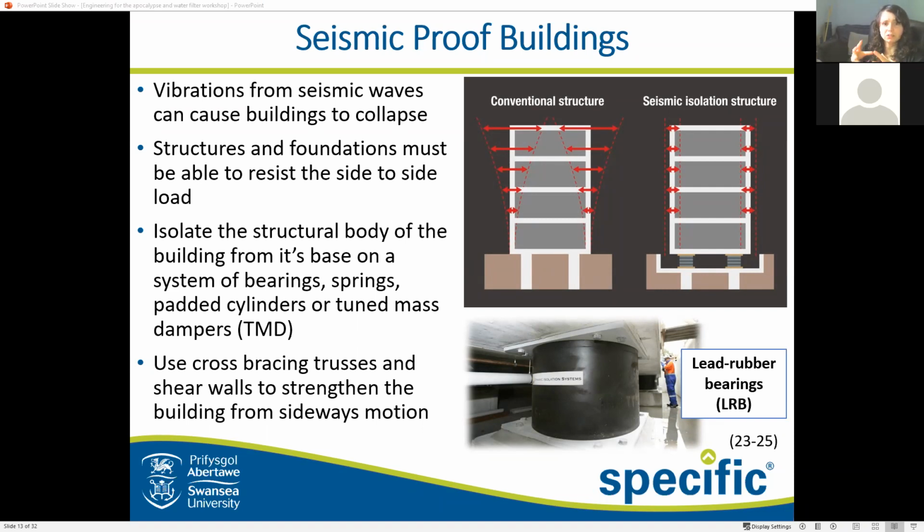So in some cases, moment resisting frames, where beams and columns can actually bend together, can be more useful, which enable the entire building to move in response to lateral force. Not that I think I would want to be in one of those buildings at that point. I think I would be sick. I get sick in a car, so I don't think that would be great, but it's a fantastic method for enabling a building to withstand these forces without giving out.